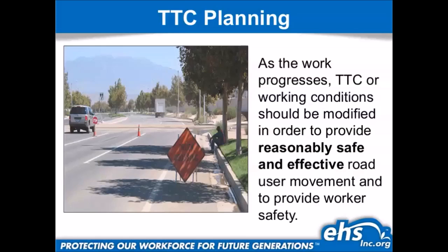If there's a flagger required at your job site, guys, you can't just set your paddle on a cone. You have to have someone step in for them for those breaks, and that person has to be qualified. Something that normally happens is that usually the flagger on projects is the guy that just got hired, and you don't know what else to have them do. And if he's not trained and he causes an accident, he's not the only one that's getting in trouble. So you want to make sure that the people who are controlling traffic know how to do it and do it safely.